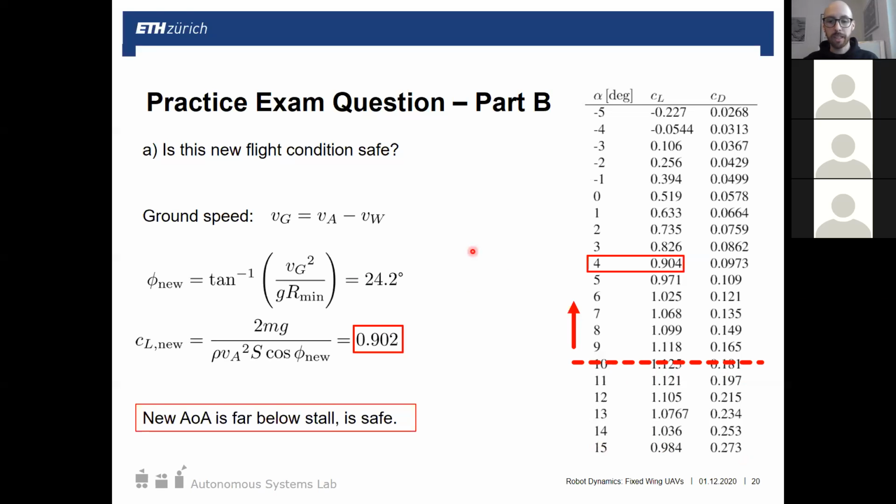In the slide from the lectures, it was showing an example of different angles of attack and what stall looks like when the flow starts to separate. Please remember, in that slide from the pre-recorded lectures, there is no set number for stall. It's very dependent on the plane. Normally it happens somewhere between 9 and 15. If you have a better airfoil, maybe you can get up to 20, but that's quite high. For most planes, stall will happen somewhere between 9 and 15 degrees.